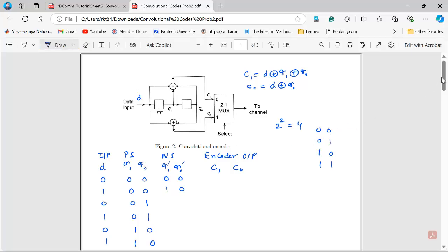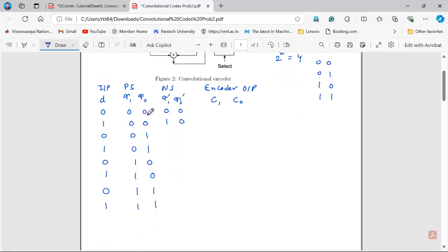Okay. So in the same way, I can write other states. So here, what is 0 shifted here? So now it becomes 0 0. The rightmost bit disappears, and you are considering only the 2 left bits. You can consider it like this. It's 1 0, it's 0 1. It's shifted basically. It's 1 1. It's 0 1, and it's 1 1.